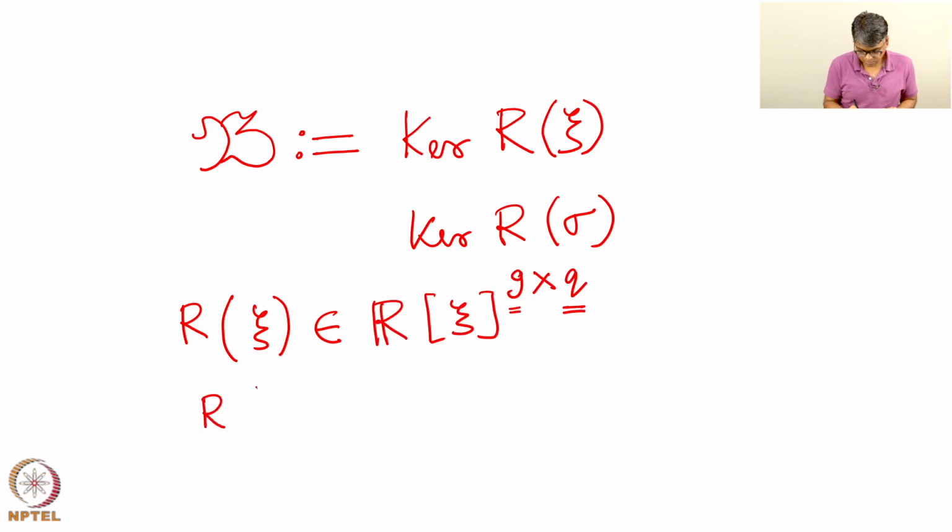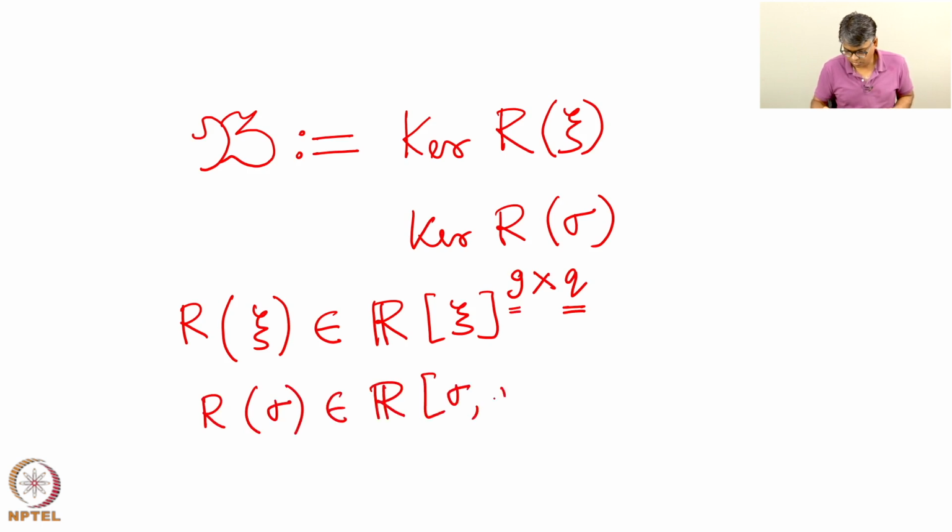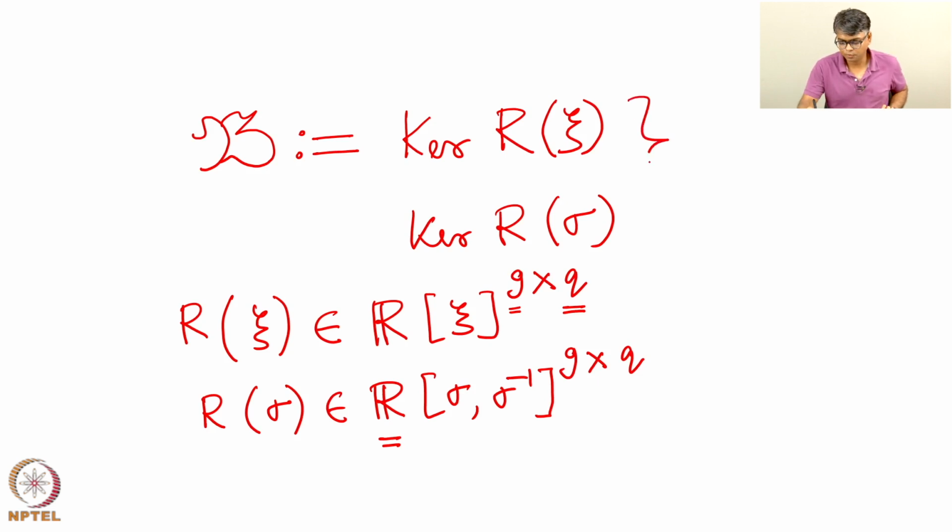Likewise, for the discrete time case, this is a matrix of Laurent polynomials with real coefficients. Before we move on, perhaps it would be nice to see yet another example of a behavioral description of systems like this.